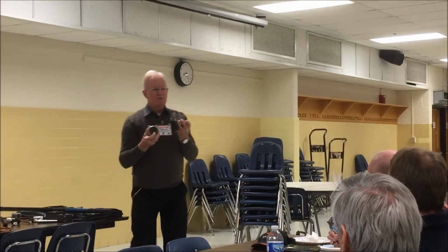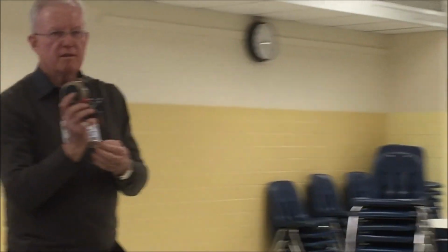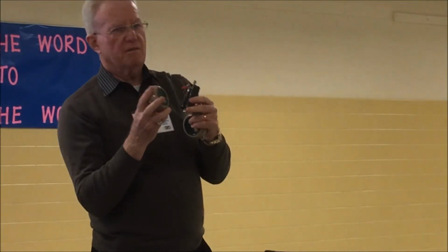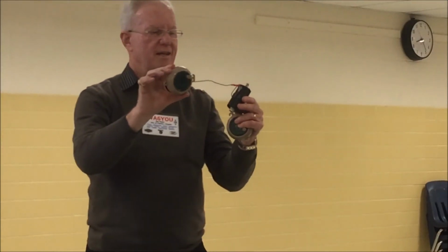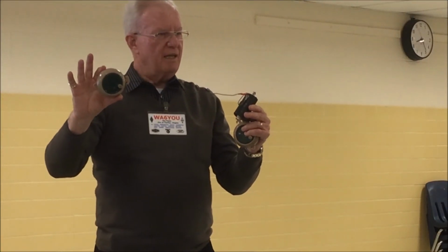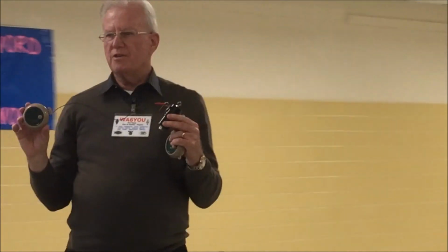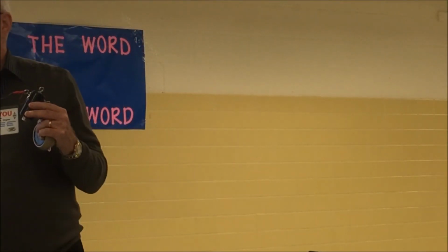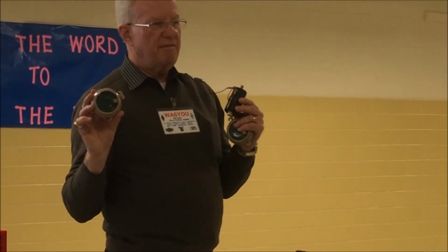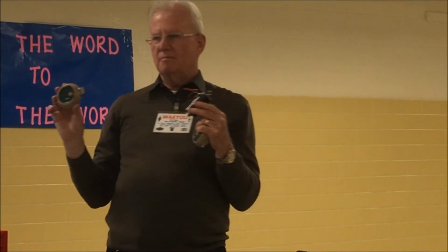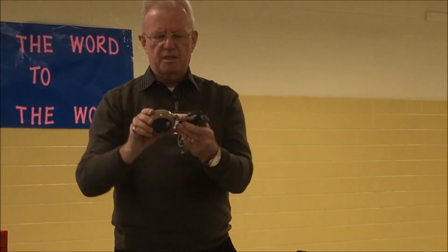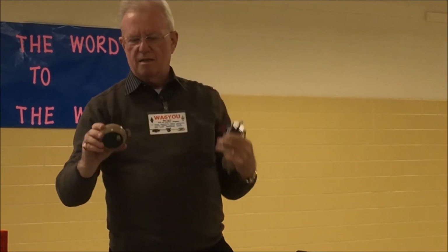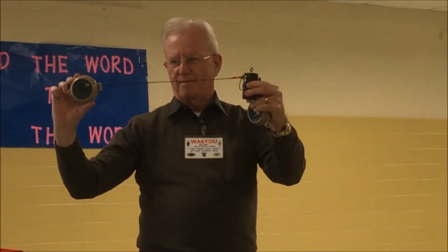And this is the yo-yo dipoles. Anybody use these? Nobody's used a yo-yo. Oh, these are great. Yo-yoantennas.com. Pull out what you need. If I need 40 meters, I pull out 34 feet. If I need 20 meters, I pull out 16 feet. If I need 21 megs, I pull out 11 feet. And as you can see, I've still got an old slinky antenna.